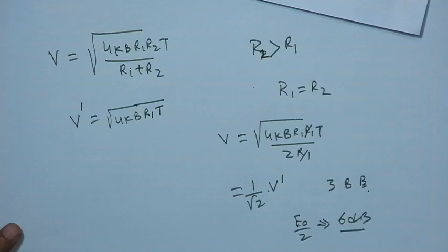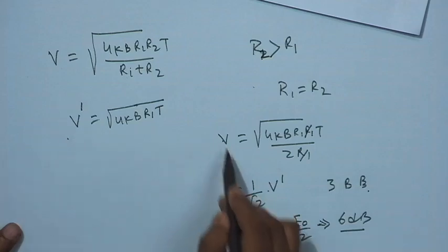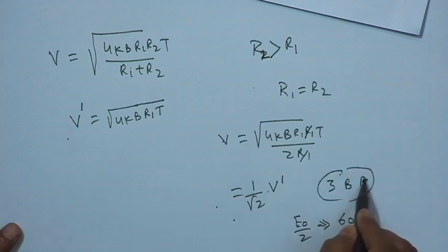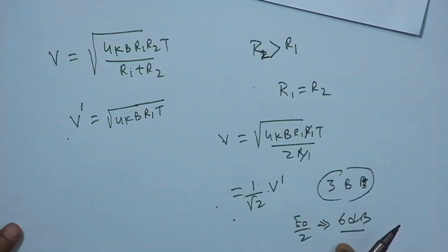So overall SNR, if it is impedance match condition, then I get 3 dB less thermal noise, but I lose 6 dB due to the impedance match available input power. So ultimately, gain 3 dB is here.